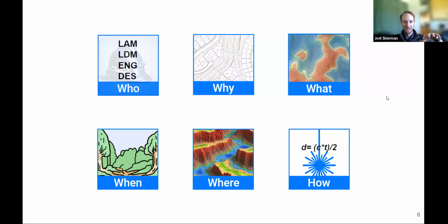But this has some bold assumptions about the accuracy of the surfaces, the actual earthen surface between each of those points. It's not going to be accurate in cases where there are high topographic changes, right? As the site changes significantly over some relatively short distance, you're going to see that that TIN model, that representation with low density points, is not going to be particularly accurate relative to a LiDAR data set where you're going to have many points per meter or square foot.